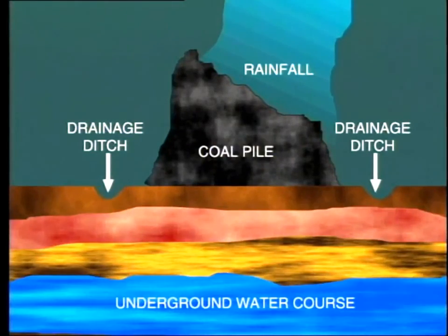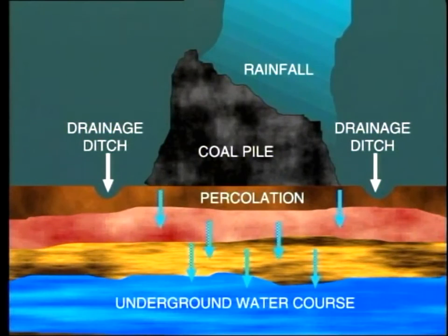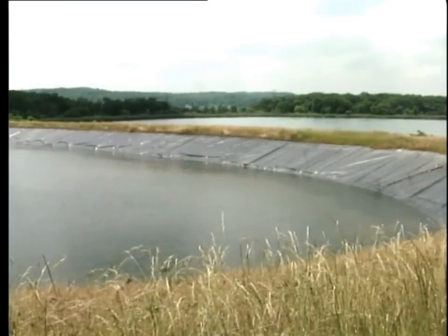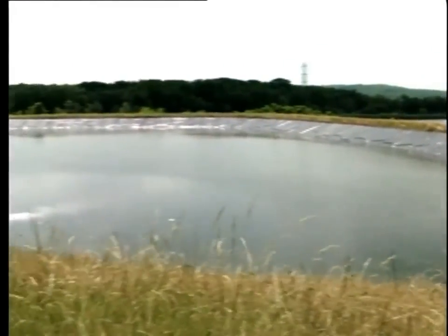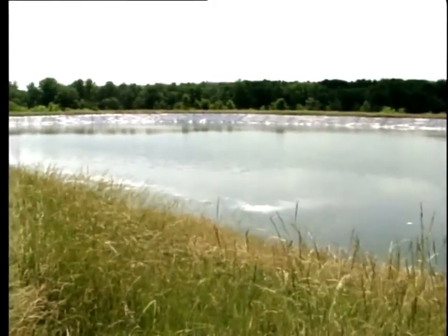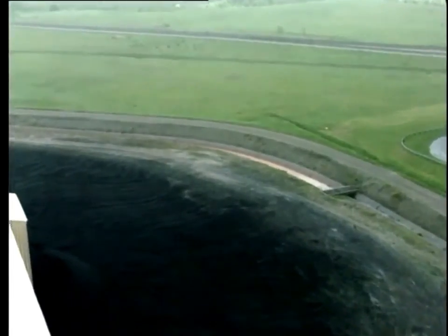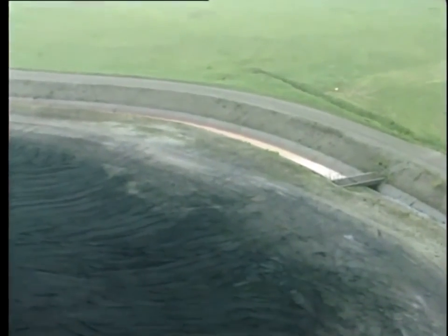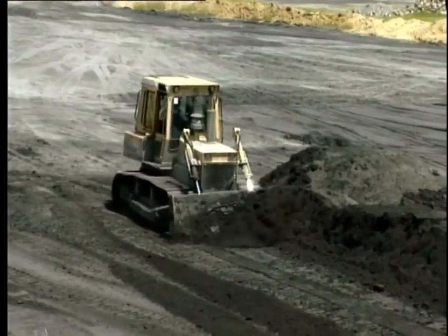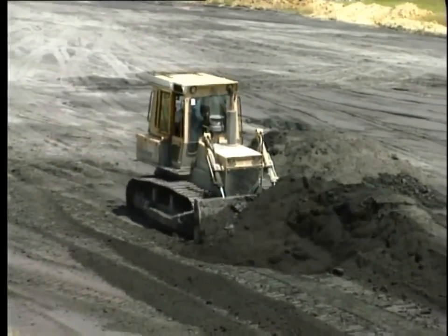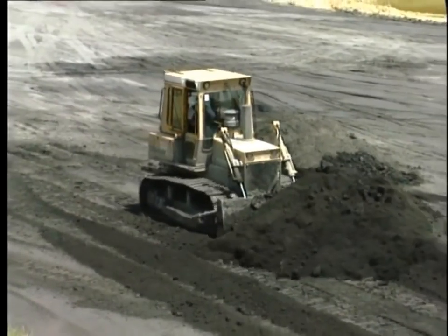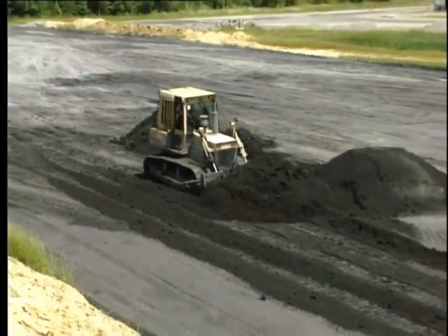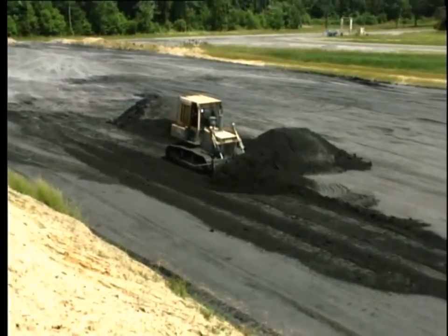This water, taking with it contaminants, some of which may be hazardous, percolates down through the earth. There it may find its way into the natural groundwater, which is often used for drinking by animals and people. Nowadays, it is necessary to install an impervious liner, usually of heavy plastic, below any of these areas, including the ash pond. Stormwater runoff must be collected and treated to remove solids. A liner is also required for the landfill area where solid waste is eventually laid to rest. In fact, there are definite rules and regulations which govern the construction and operation of a certified landfill site.